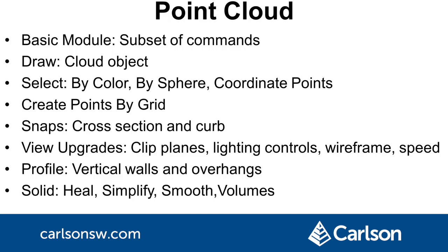For drawing the cloud to CAD, there is a new method to create a point cloud object, which allows for viewing and snapping to large clouds in the drawing. There are new ways to select, including select by color, by within sphere at pick point, and controls whether to select cloud, solid, or coordinate points. There is a new function to create coordinate points at a grid interval.